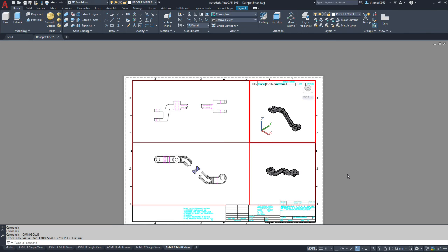Alright, again, I'm not going to show you guys dimensioning lines, that kind of stuff. You guys should be getting pretty good at that by now. So the next step is to put your center lines on everything. Don't forget to lock your viewports once you have them scaled. Save early, save often. You'll retire early if you do that. And make sure you make a complete drawing. The assignment should have an example drawing in JPEG.